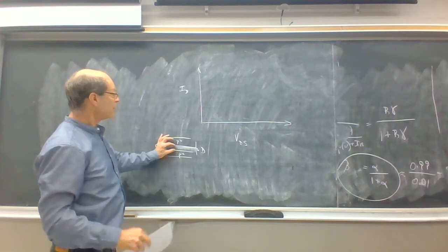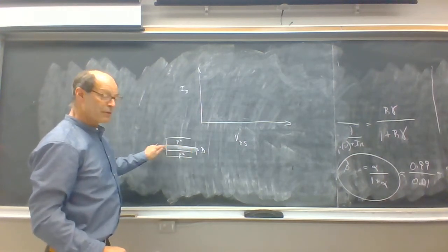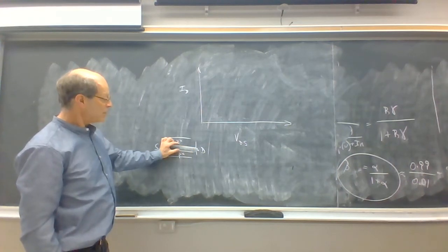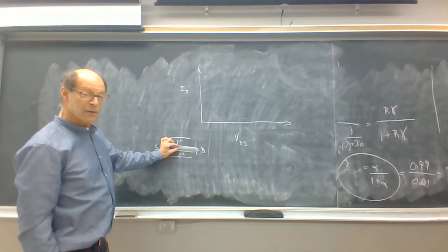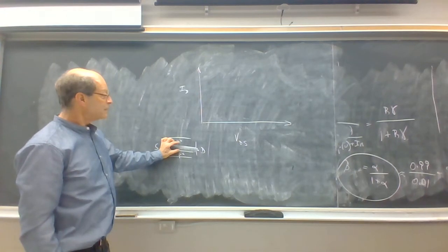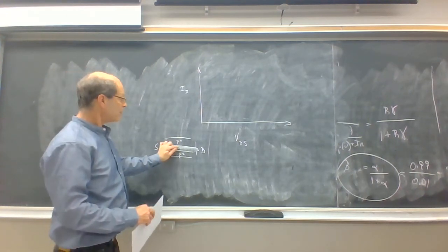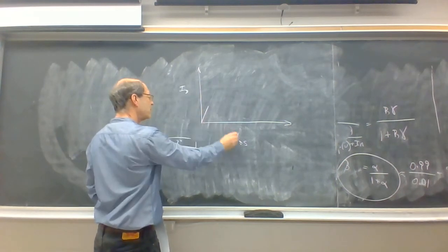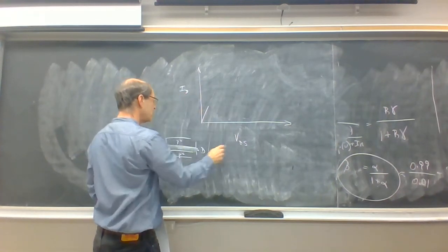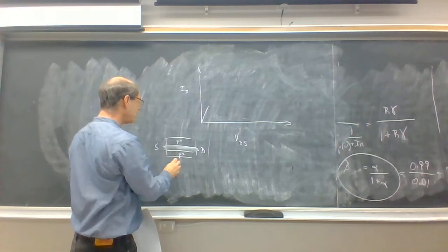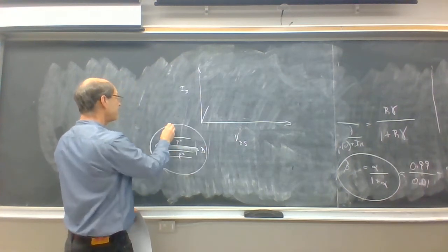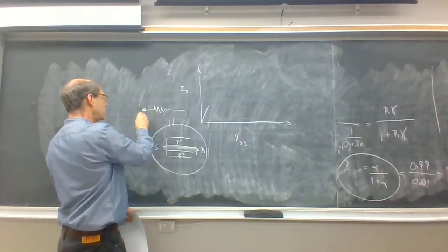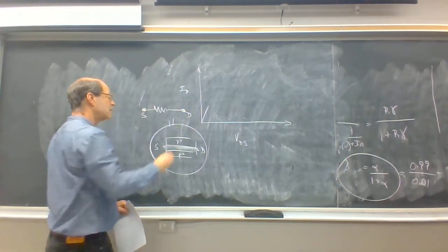And of course, the resistance of the effective resistor that exists between the source and the drain depends on the thickness of this channel. So the resistance actually determines the slope of the drain current versus the drain source voltage, because you can think of this as a resistor connecting the source voltage to the drain voltage.